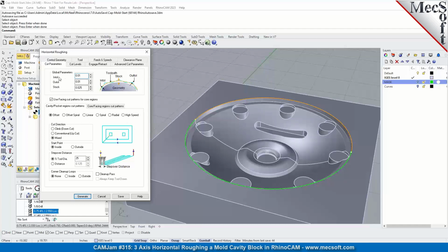So the in tolerance and out tolerance, the way the tolerance is calculated in 3-axis is different than it is in 2-axis. In 2-axis, the tolerance only applies in the X and the Y side walls, say a pocket, for example. In 3-axis, the tolerance is calculated across the surface contour of the surface.